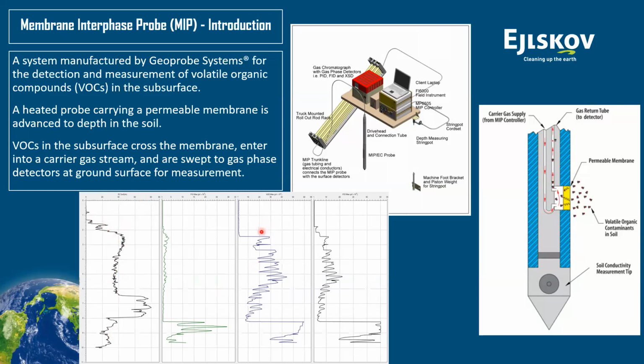Based on the historical information, we know that the aquifer was approximately 8 meters below ground level. Here we could definitely identify the presence of a source, in this case a chlorinated source. And as soon as you enter the water table, you could definitely see a large amount of contamination being present. All this, though, has to be quantified.